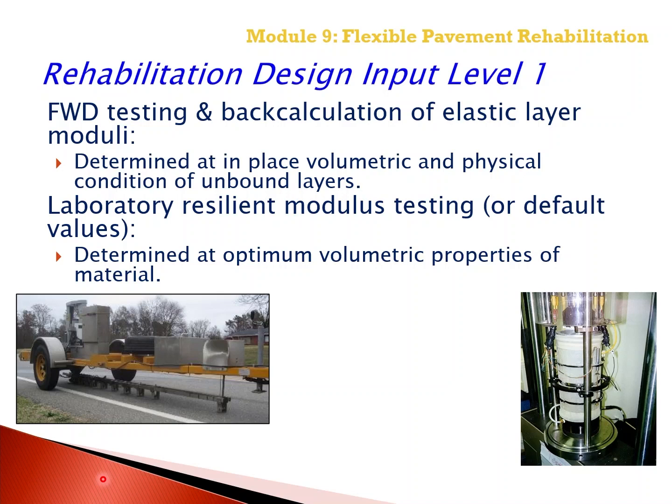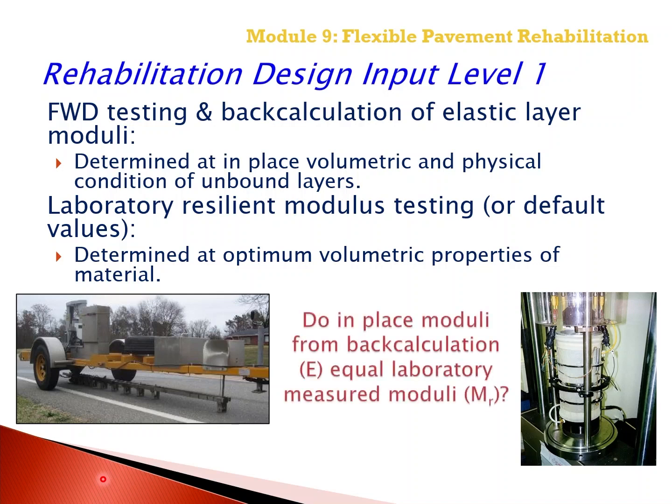The laboratory resilient modulus testing or default values included in the Pavement ME software represent the condition at optimum volumetric properties of the materials. So the question is, do the in-place moduli from back calculation of the unbound layers equal the laboratory measured modulus at the same water content and dry density?